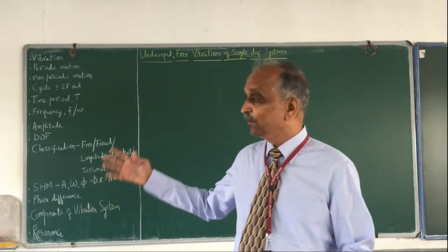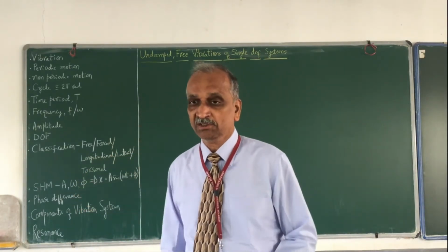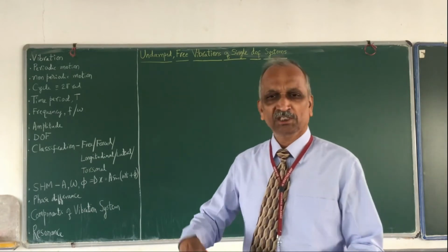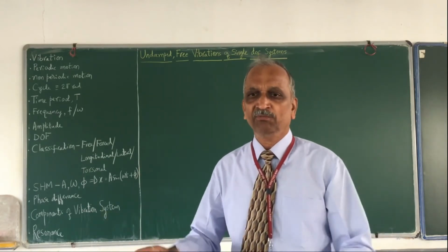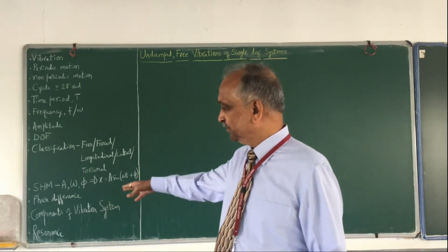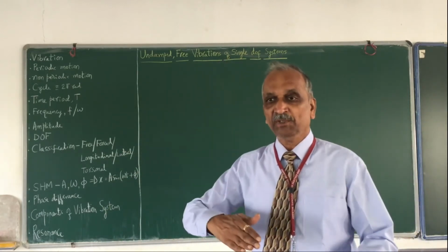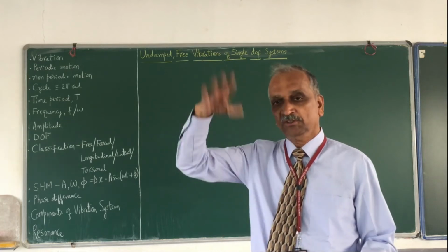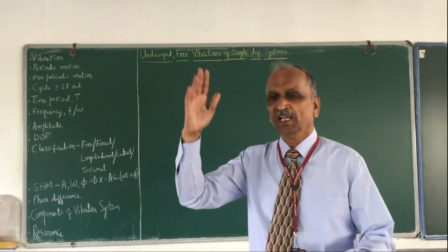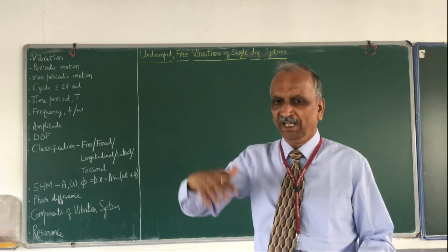Then what is the problem with resonance? If you operate the system at resonance, then very soon the system will collapse and fail. If you continue to operate the system at resonance, you will find the amplitudes of the vibrations continuously increase, and in no time reach very high.